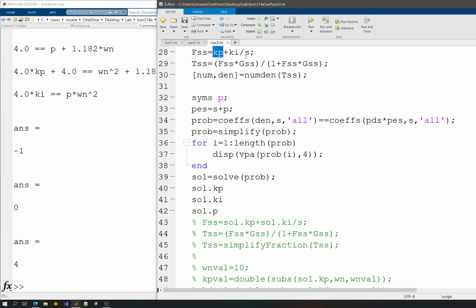And you can also end up with an I controller which doesn't have a Kp parameter or is set to 0. Then you have a different controller. But keep in mind that all P-type controllers are a subset of PI controllers, because it is a special version where Ki is 0. So if you think of it that way, it is a subset of the possible solutions.